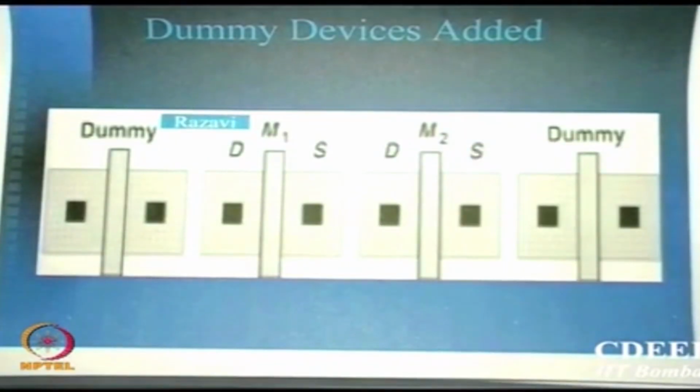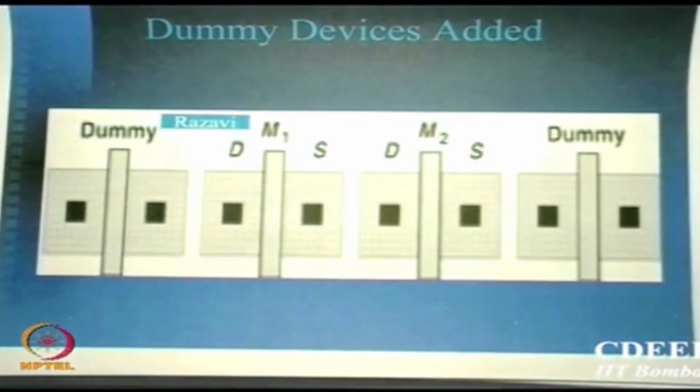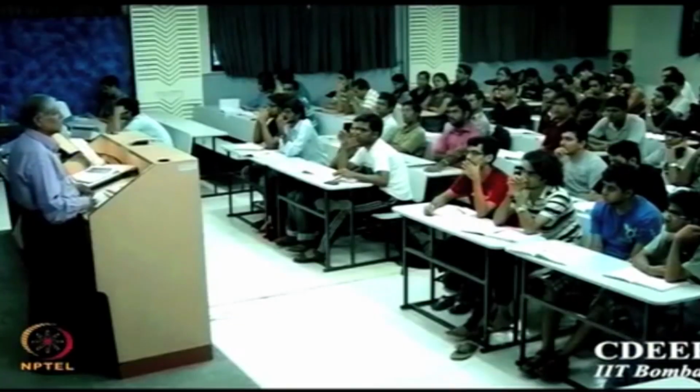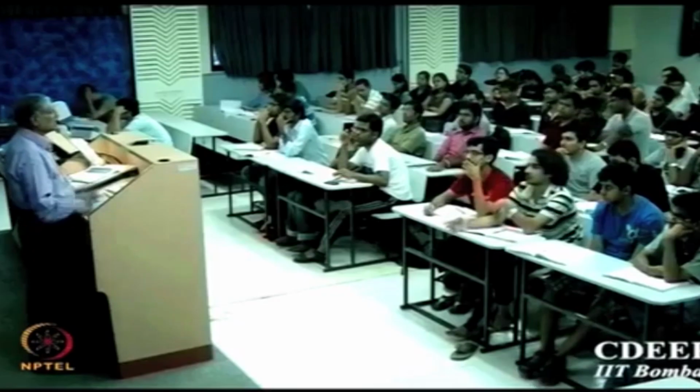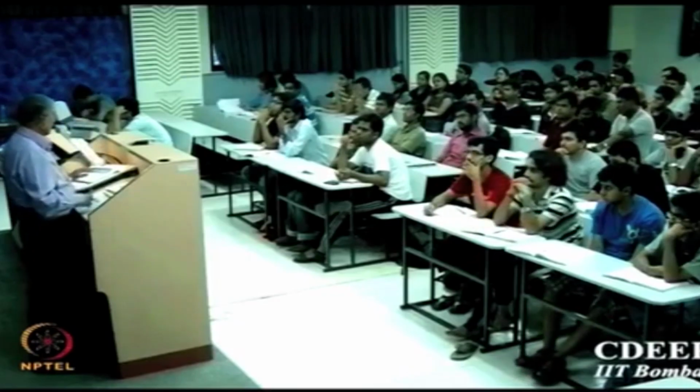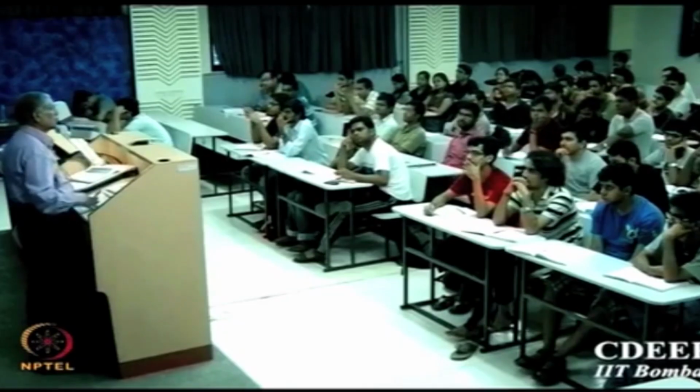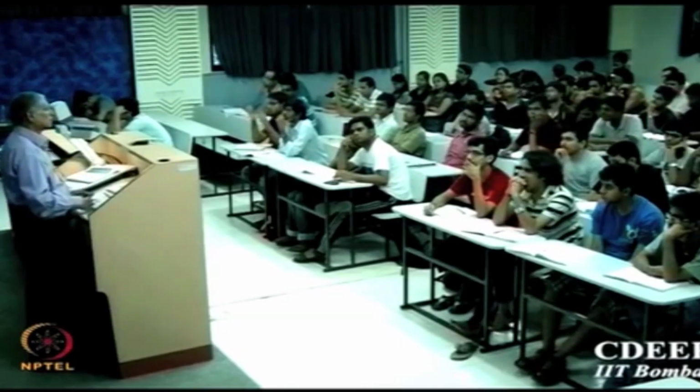So to create a symmetry, I create dummy transistors on the left side or right side. It's called bias. Whatever bias I see on one side, I see exactly identical on the other side. These are called dummy transistors. At least if not transistors, at least put polylines, this poly to this poly, because that is where the implant edge comes. So the minimum requirement in analog is that every transistor, if they are not together, must be surrounded by parallel polylines to create symmetry for implants. Is that correct? Yes.